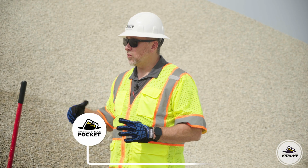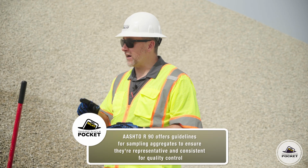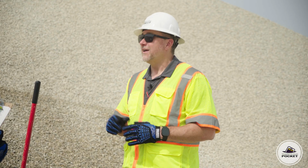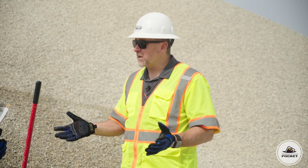So today, we're going to sample some coarse aggregate here from the quarry. We're going to use the guidance that's in AASHTO R90, which is the standard practice for sampling aggregate products. But that standard covers more than just coarse aggregate, right? It does. I'm glad you've reviewed the standard. Not only does it cover more than just coarse aggregate, it tells us all the different places we can sample.